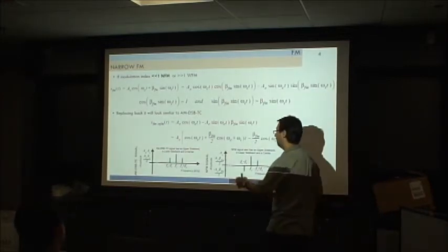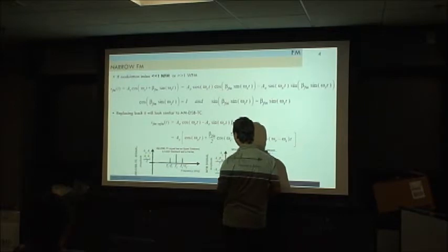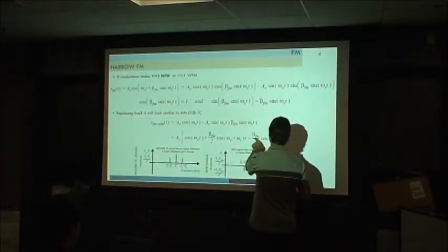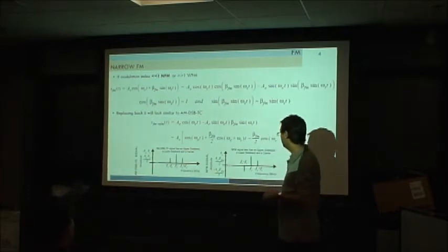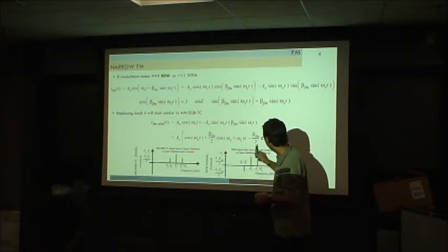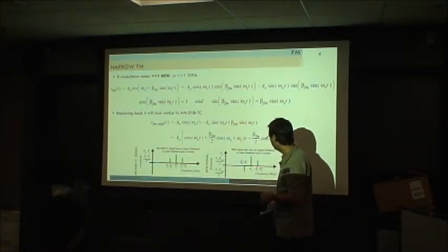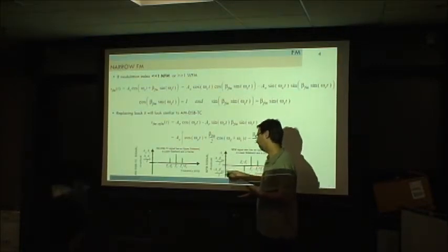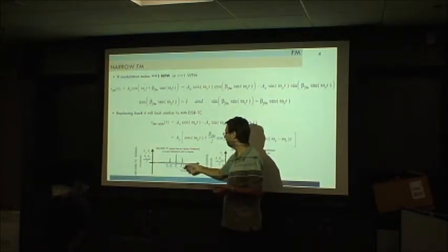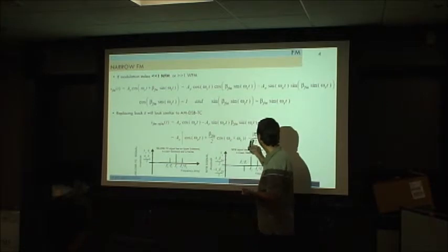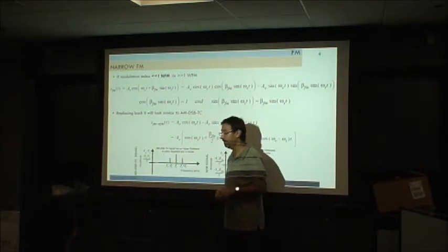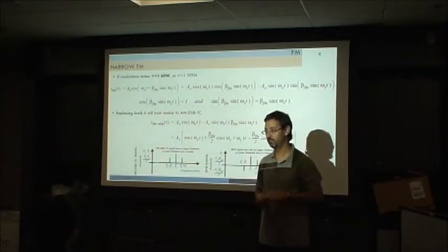So we have some frequency component here, and then we have one component going up from the carrier and one component going down from the carrier. So if we represent this, is this one, because we have this minus here. So this doesn't look like too much like this. It is, okay? We place a plus there. It will be an AM dual sideband transmitted carrier, okay?